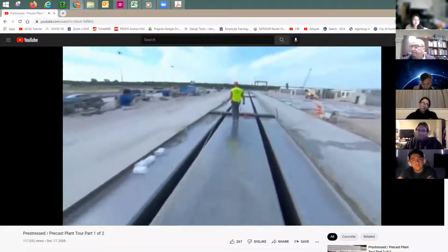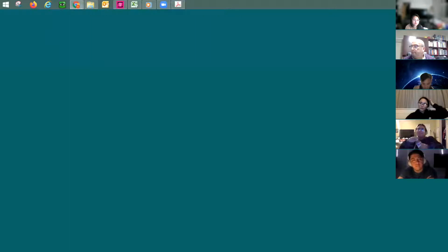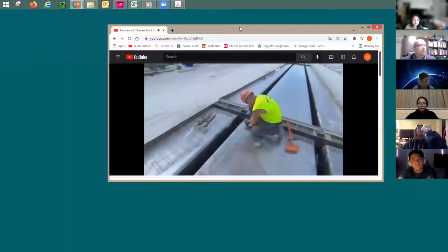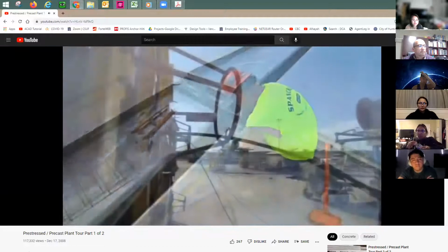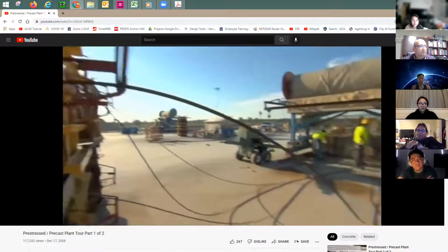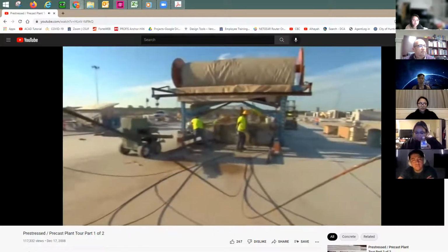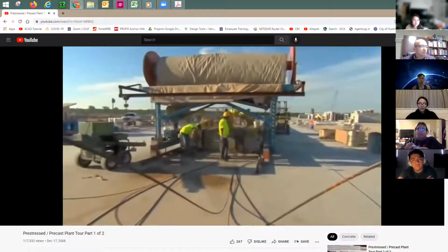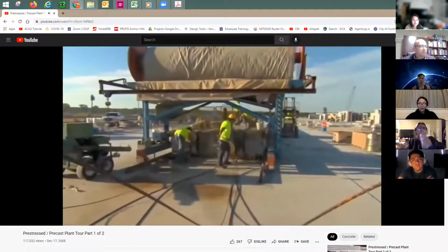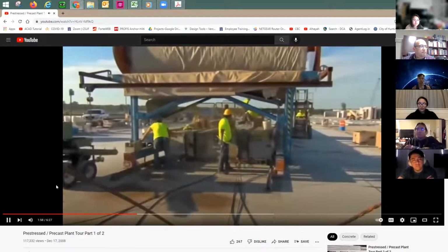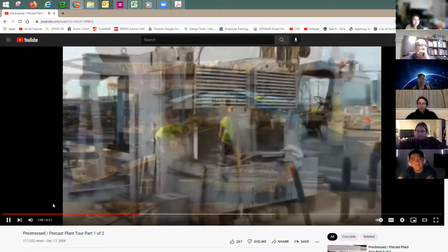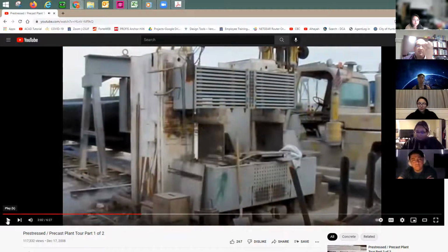This particular bed is set up for 5 double T's, each about 60 feet long. The bed has a total length of 400 feet. This is a self-stressing form, where the form itself is designed to take the total pre-stress force in compression, and also to handle the eccentricity of the strands. The strands are the same as the tendons, same as the cables. So you can use any of these terms.